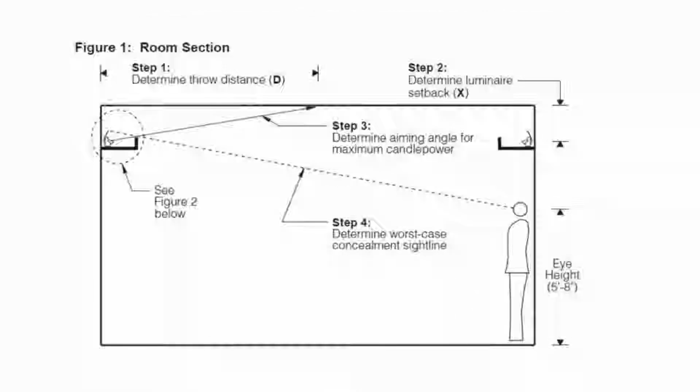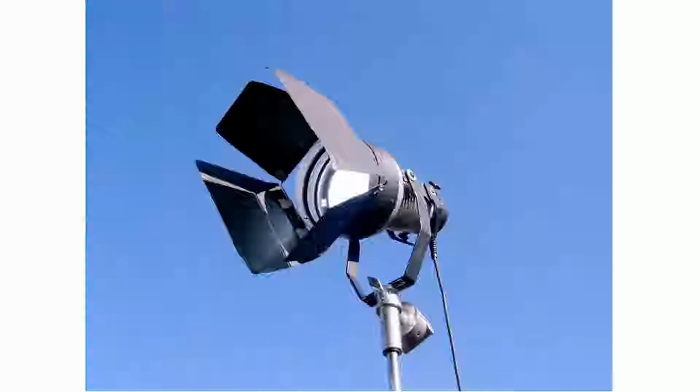And even in things like recessed luminaires that are up in, say, a cove, you can calculate where the eye height is. We know, because we know how big people are, more or less, at least the range. And then we can figure out what the cutoff angle is going to be. Now, some fixtures, such as theatrical fixtures, are going to have their own little cowls.